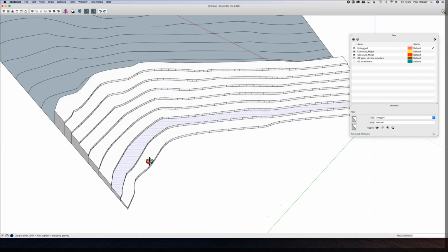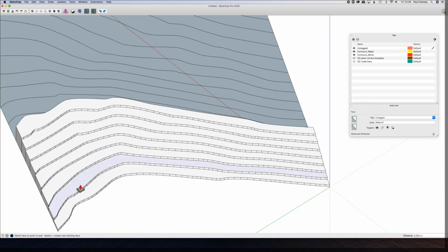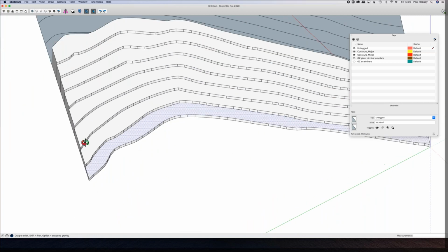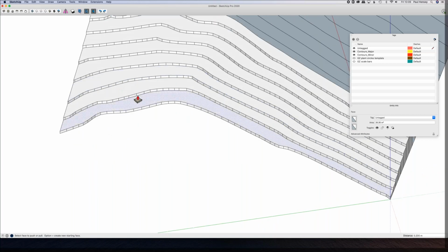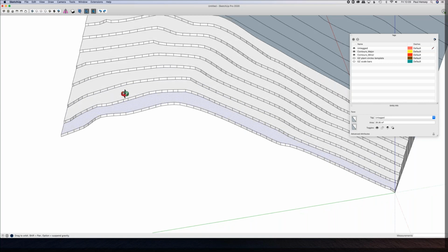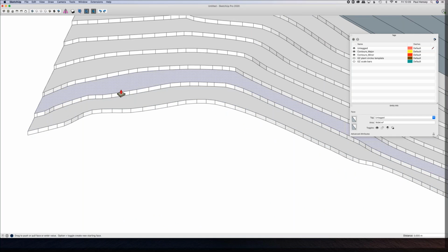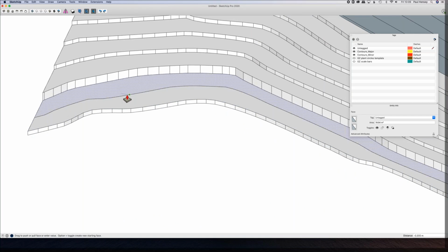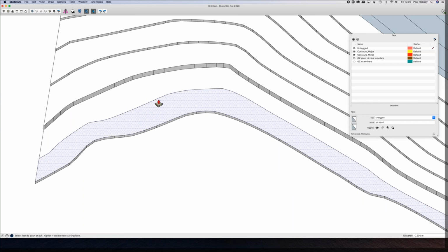And to illustrate, let's say we've got a bit of a bulge here, and there's something that I want to do. I want to reshape the land. Well, that would be quite difficult. It needs some very skilled work in using the sandbox tools. But what I can do here is I can pull down this geometry, and then I can draw in a new curve.